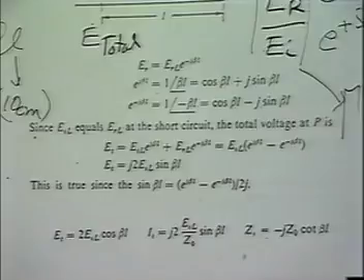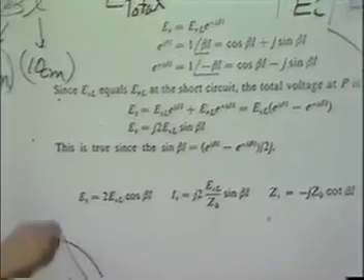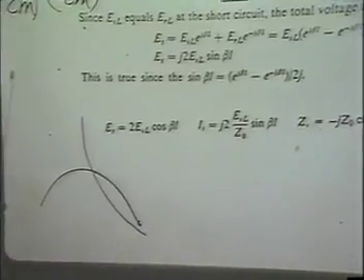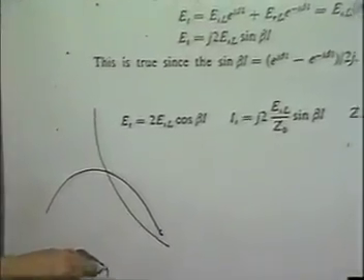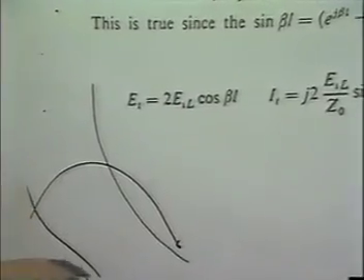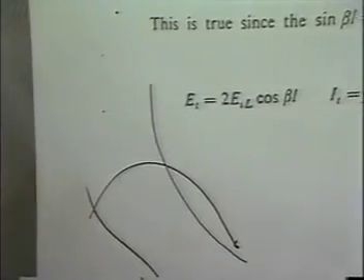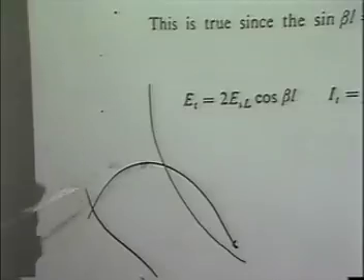Because if you have a short circuit like this, you know it's going to be like this. It's going to go to plus infinity. Then what happens? It becomes capacitive and goes from minus infinity back up to 0 again. Because one place is inductive reactance, and on the other side it's capacitive reactance. So that's this tangent-cotangent function.